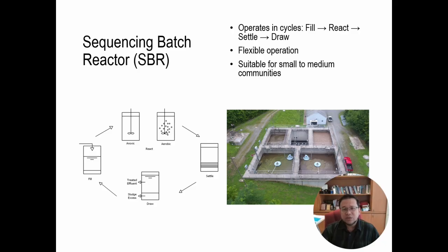The sequencing batch reactor, or SBR, is a flexible alternative that performs all the biological treatment steps, aeration and sedimentation, in a single tank, but at different times. It operates in a time cycle with four key phases. There are fill, react, settle, and draw.